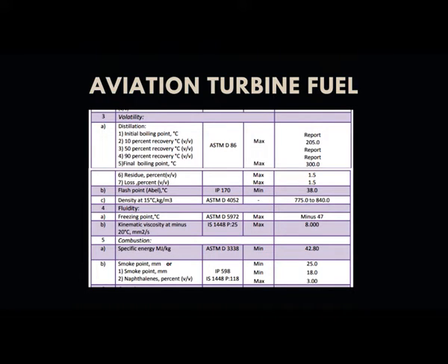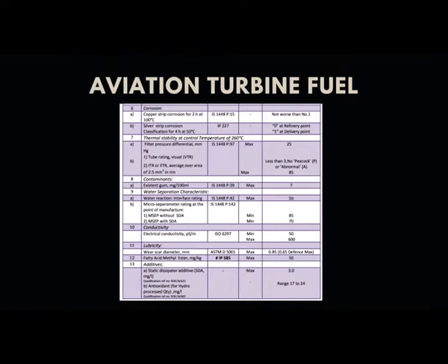Freezing point is an important test for aviation turbine fuel, because when the flight is flying at an altitude of more than 30,000 feet, at that particular temperature this fuel should not get frozen. Because of that reason, the freezing point is very much important, and the freezing point defined in India is minus 47 degrees centigrade. Thermal stability at controlled temperature is an important test.